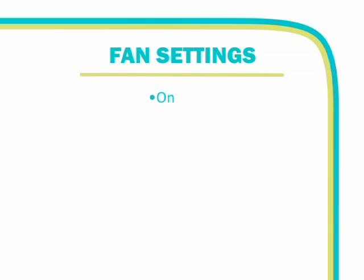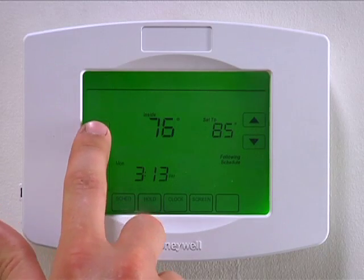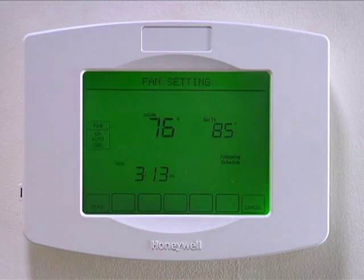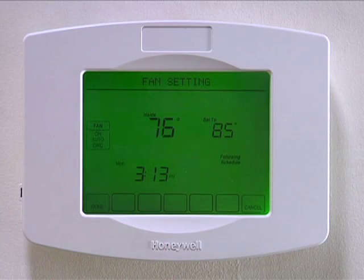On, the fan will operate until the setting is changed. Auto, the fan will operate only when the heating or cooling system is on. Circ, which stands for circulate, the fan will operate when the heating or cooling system is on and randomly about 35% of all other times. To select a fan setting, press Fan to scroll through the fan settings. Once you have selected the desired setting, press Done.